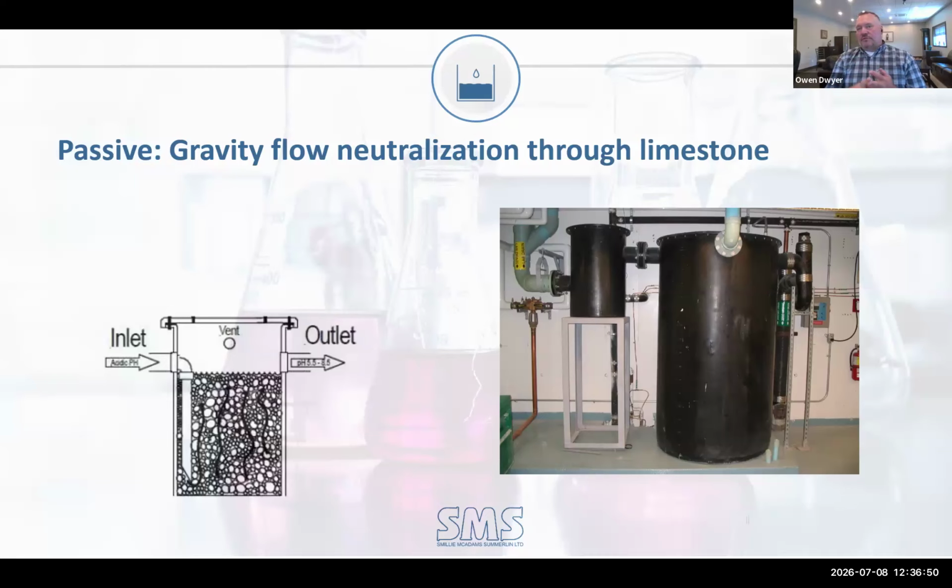Downstream of the interceptor, you'll see the bigger tank, which is the neutralization system. That would be full of calcium carbonate limestone. You can see on the left side is all polypropylene. The vent at our 6 o'clock in that image on that big tank would be the vent. And then you can see on the right-hand side, it's cast iron, because at that point, you're no longer considered corrosive. Now you can drain with traditional materials.